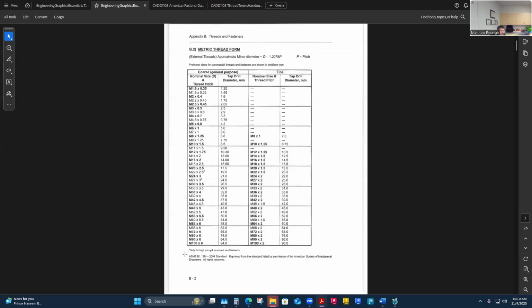Yeah, I guess that's just a little footnote to know that, hey, that's for that specific application, high strength structural steel fastener. Anytime I'd see that, I'd think that means that's an expensive fastener. So that's probably the major reason why I would want to know that, or I'm buying a way more expensive fastener than I probably need. However, that's the only one in that size.